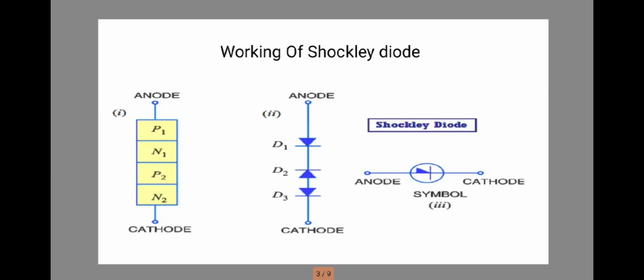At this point, diodes 1 and 3 would go into reverse voltage breakdown. The reverse current flowing through them would rise rapidly and the heat produced by this current flow could ruin the entire device. For this reason, a Shockley diode should never be operated with a reverse voltage sufficient to reach the reverse voltage breakdown.